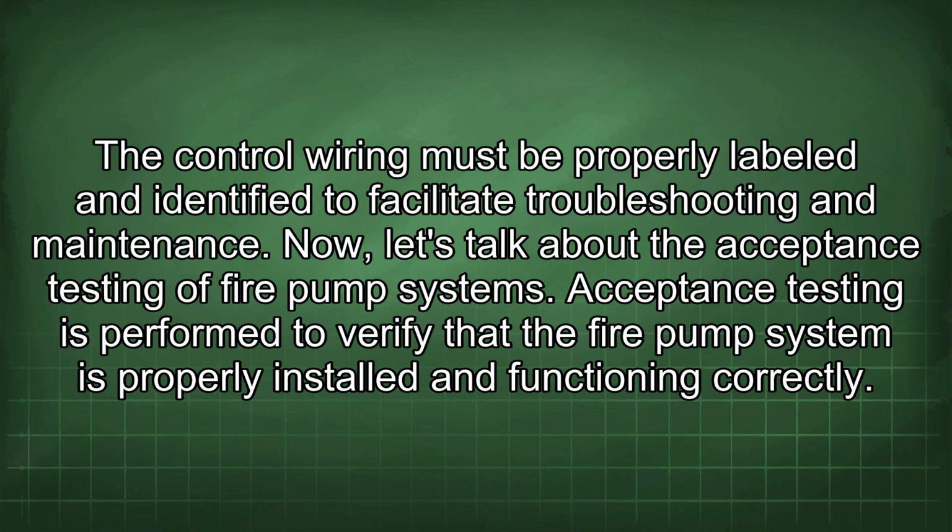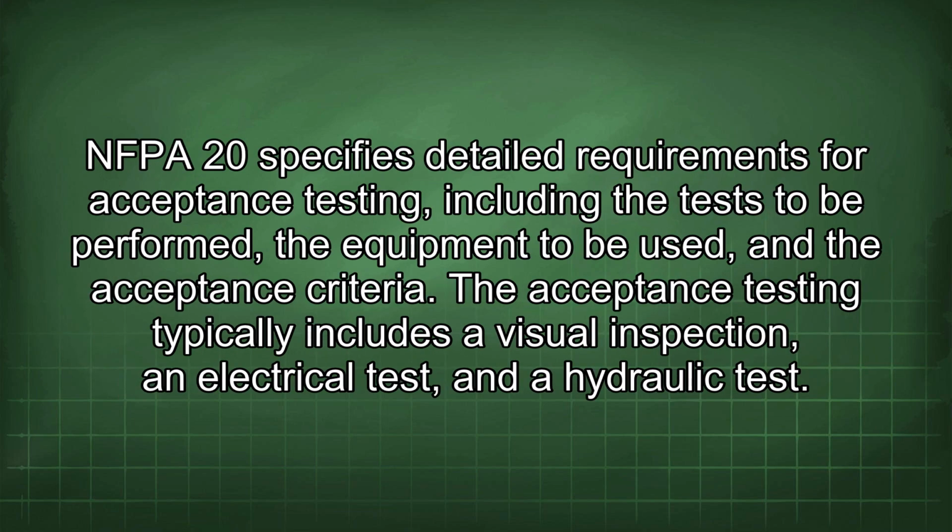Now, let's talk about the acceptance testing of fire pump systems. Acceptance testing is performed to verify that the fire pump system is properly installed and functioning correctly. NFPA 20 specifies detailed requirements for acceptance testing, including the tests to be performed, the equipment to be used, and the acceptance criteria. The acceptance testing typically includes a visual inspection, an electrical test, and a hydraulic test.